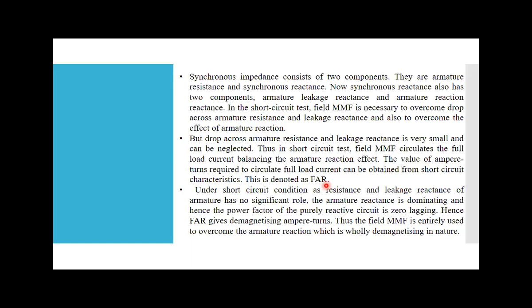Now under the short circuit condition, as the resistance and the leakage reactance have no significant role, we already neglect them. The armature reactance is dominating, as I already told you, and hence the power factor is purely reactive, zero lagging.